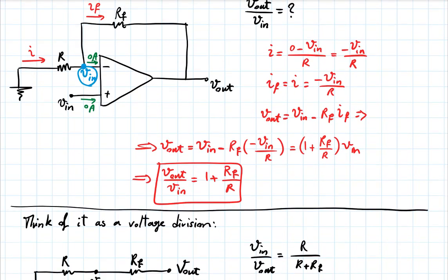Say again, which node voltage? The blue point. Oh, question here. Why do I know that the blue node there is at Vin? And the answer is, when I start the solution, I don't know. What are the steps of solving this problem? What are the things that I do know? I know that the voltage here is Vin. That's all I know, right? But then the next thing I do is to look at what the op-amp does. The op-amp is an ideal op-amp, okay?